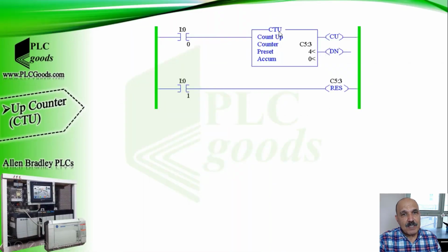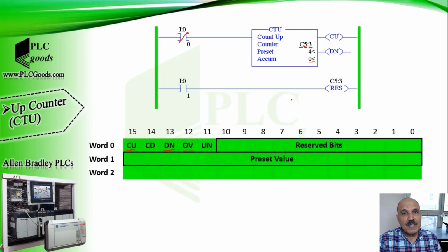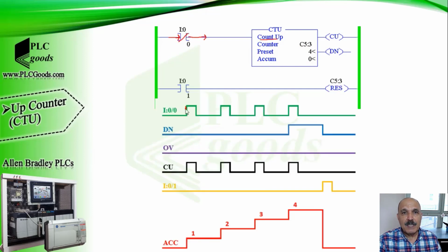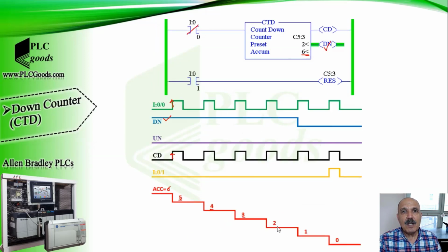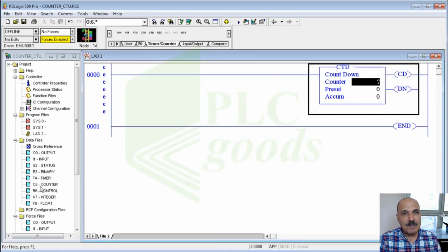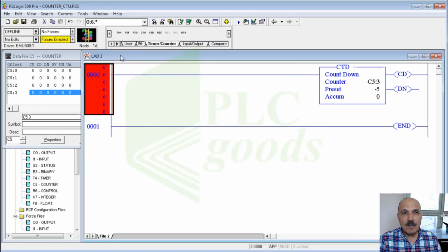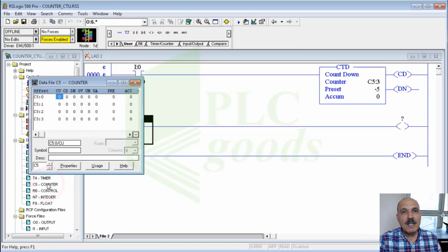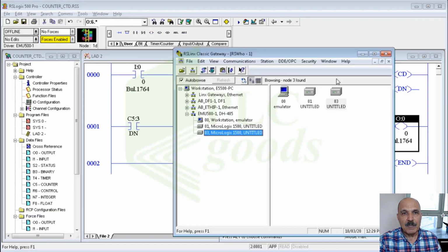Video lesson number 6 introduces up and down counters in PLC programming for event counting, explaining how these counters increment or decrement their values based on specific input conditions. It covers fundamental ideas, including overflow and underflow conditions when counters exceed their upper or lower limits.